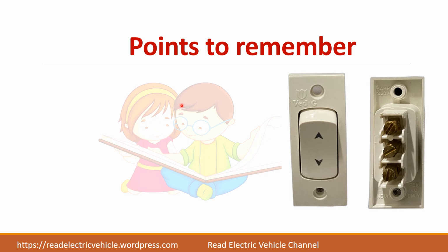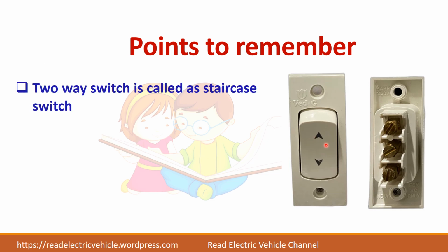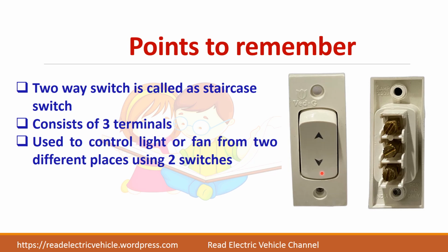So let us summarize what we have learned. So it's about the two-way switch, which has three terminals, which can be used to control a single lamp from two different positions.